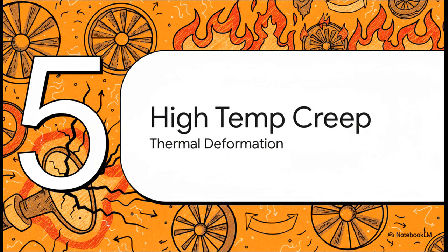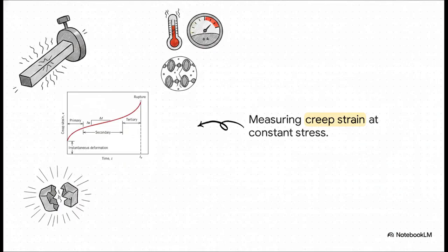All right, bringing us to Section 5, Creep at High Temperatures. Let's look at our final failure mode. Creep is the slow, relentless deformation of a material under a constant stress in high-temperature environments, usually above 40% of the material's absolute melting temperature. Think jet engine turbine blades or high-pressure steam lines. This graph tracks its inevitable life cycle, plotting creep strain against time from the initial load all the way to a disastrous rupture. But we can't exactly wait 20 years to test a turbine blade's lifespan in a lab.